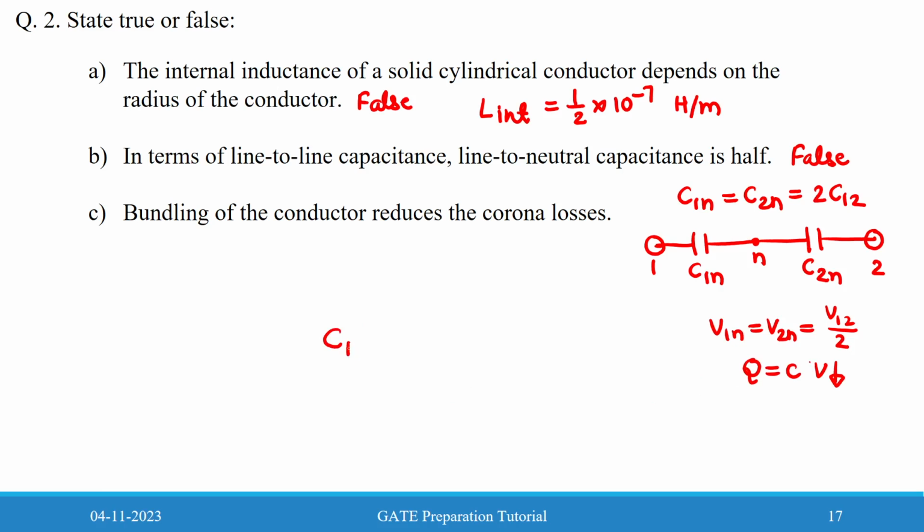And remember this expression only, the capacitance with respect to neutral, because generally they ask for capacitance calculation with respect to the neutral point only. If this is for a single phase wire, not a bundle of conductors, then you only have to use R in place of GMR.